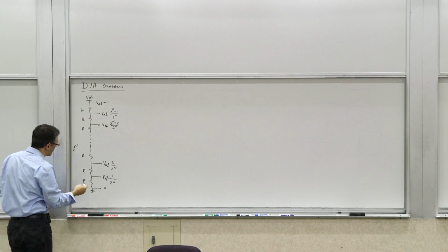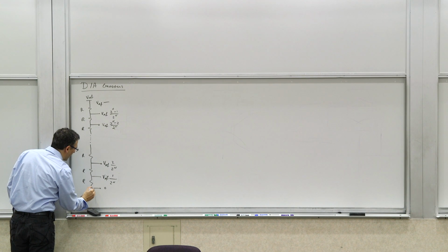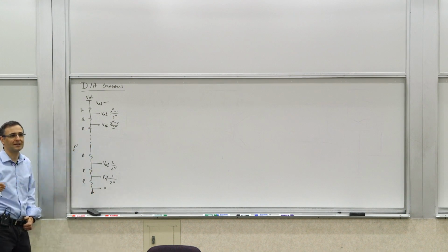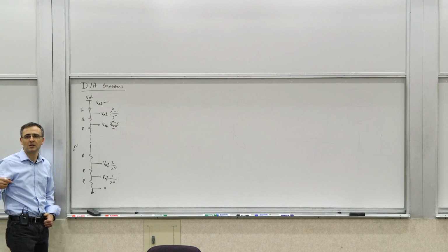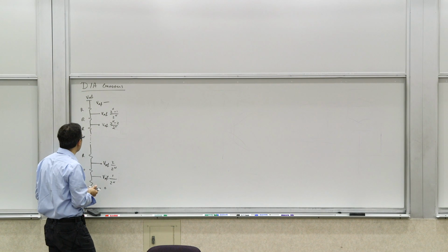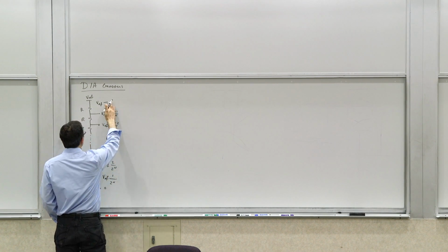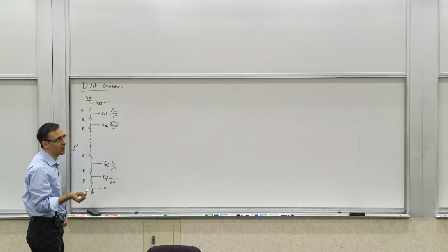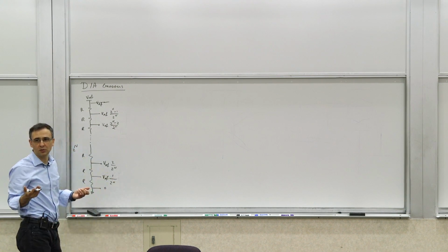We talked about this briefly, and you can see that this is ideal, of course. There would be mismatch, and if there's mismatch or if there's gradient in them, that would correspond to INL and DNL in the response of the DAC. But now, one of the things that you would like to do is just take these voltages and select the right one. So that's the simplest thing that you can do as a D2A.